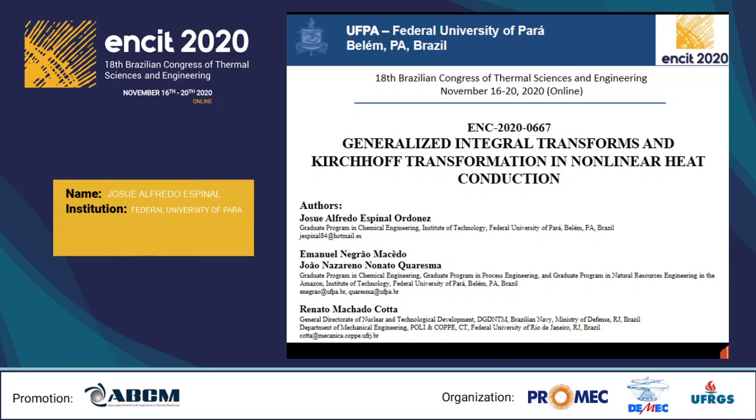The Generalized Integral Transform Technique (GITT) is combined with the Kirchhoff transformation in solving transient nonlinear heat conduction problems, considering temperature dependence on both the thermal conductivity and the thermal capacitance. The hybrid methodology is employed with a convergence acceleration strategy based on a quasi-steady filtering scheme. The approach is demonstrated for a test case based on boundary conditions of the second and first kinds.